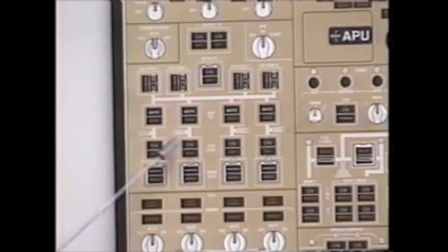Generator control switches. During the cockpit setup, your captain's going to turn the generator control switches on, but they will still stay off because the generators are not physically turning. It's impossible for the relay to close. IDG disconnects. If you disconnect an IDG, maintenance has to reconnect it on the ground with the engine shut down. There's an amber drive light in each IDG. The amber drive light illuminates for IDG high oil temperature or IDG low oil pressure.